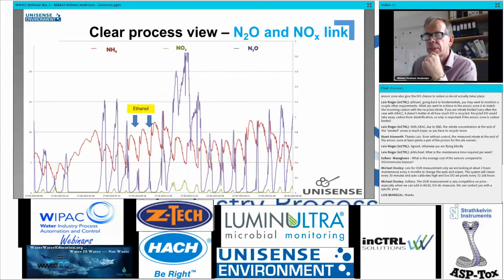So if we enhance the denitrification, then we can lower the nitrous oxide quite significantly because then it's processed to free nitrogen. And just to prove this, over-aerating, as you heard before, doesn't help a lot in terms of turning over more ammonium, but what it generates is a lot of nitrate, because now the nitrite is becoming nitrate, from NO2 to NO3, and then the nitrous oxide starts to really increase, and it maxes out in terms of our sensor sensitivity. So carbon control and ammonia control are really important.